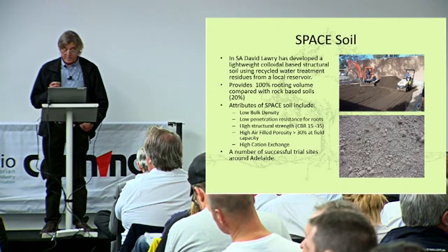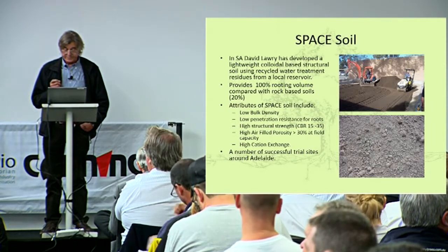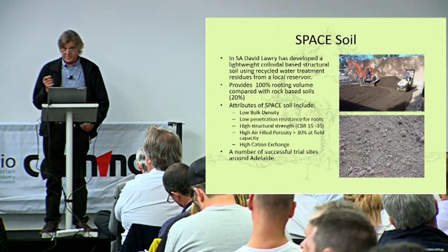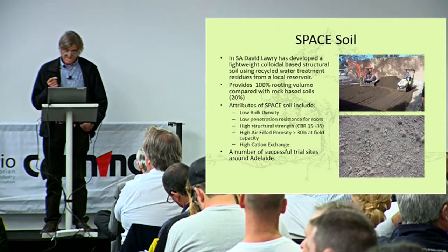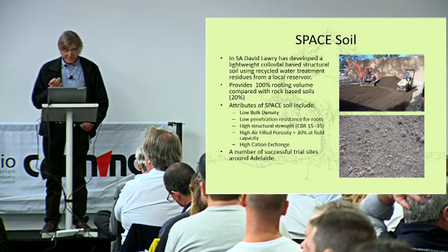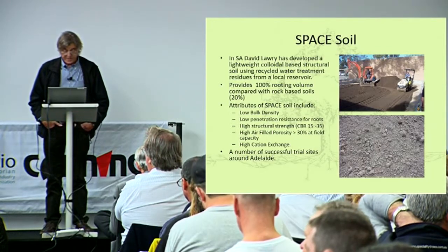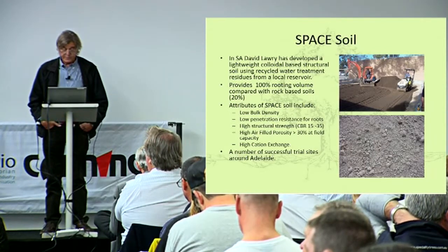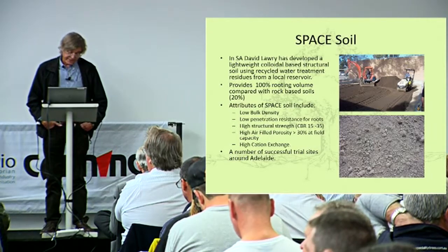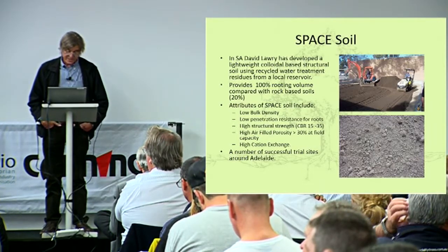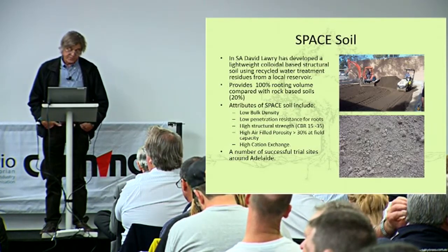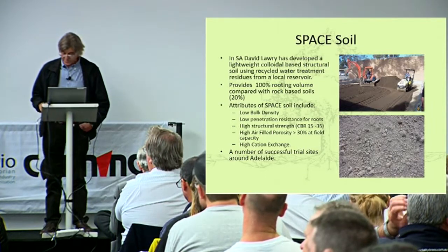It's made up of colloidal waste products from South Australian reservoirs, and has a number of desirable attributes, including low bulk density, low penetration resistance for roots, high structural strength, high cation exchange, and a number of successful trial sites around Adelaide where this has been installed.